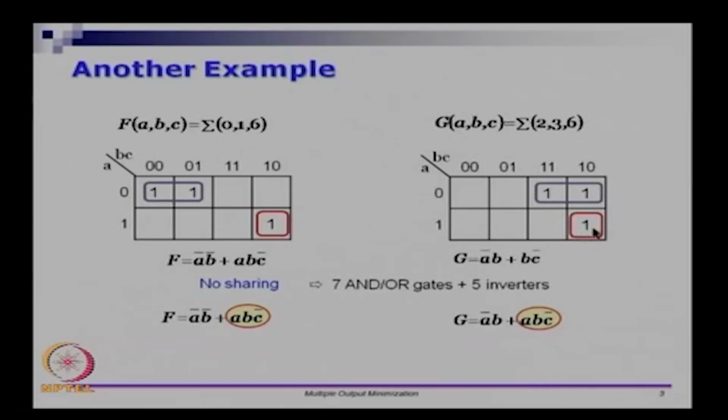And this is interesting. So when I talked about K map, I always said you should go and maximize the number of ones that you are grouping, and the argument is if you maximize the number of ones that you are grouping, the number of literals go down, and therefore the number of AND gates will go down if you are doing a sum of products. So if I group 8 ones together, then I am knocking off variables, right. However, here I am making a case for not doing maximal grouping.